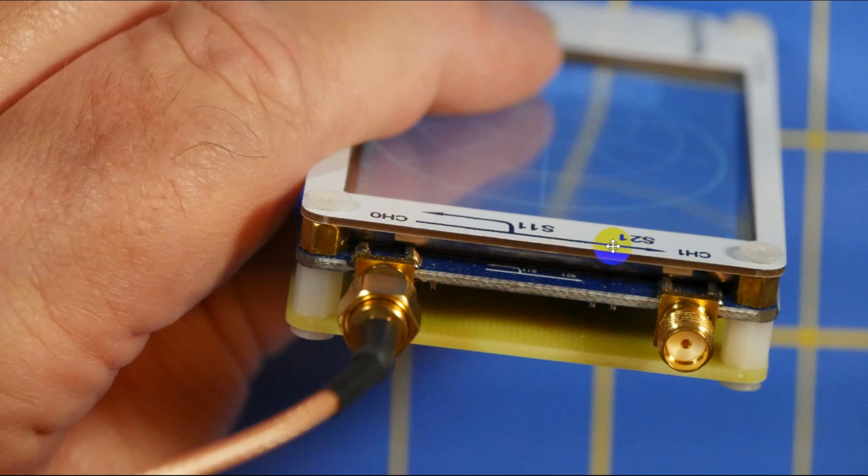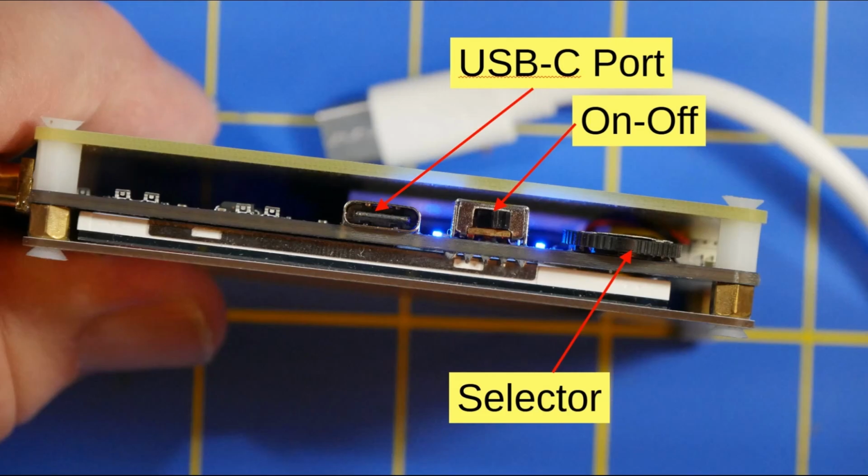This is the business end of it here. This is channel 0, channel 1. Now note the difference here. There are 4 scatter parameters used in amateur radio. This is the first one. S11 happens to be SWR. S21 happens to measure the amplification. It'll put a signal out here and put a signal in here. So it's a little different. Right here, we're using it just for SWR. And it is the cheapest you can get on the market for an antenna analyzer, and quite a good one at that. Over here, you see the USB-C port.